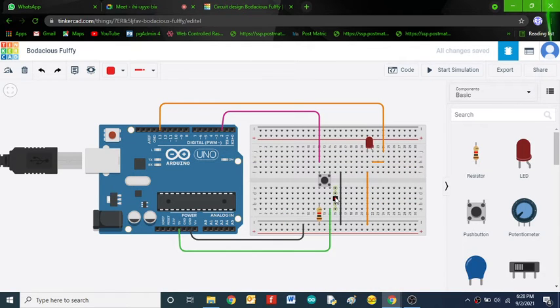So my requirement is to turn on the LED based on the push button. Now the requirement has changed. When I press this push button continuously 2 times, only then do I need to turn on the LED. When this push button is pressed continuously 4 times, the LED should be turned off. This process goes on repeating, right? That is very important.